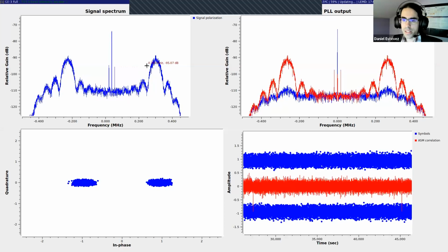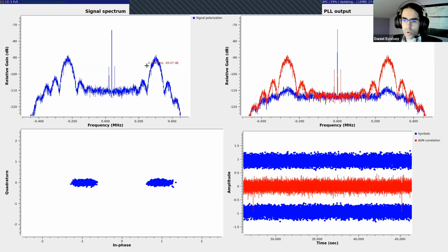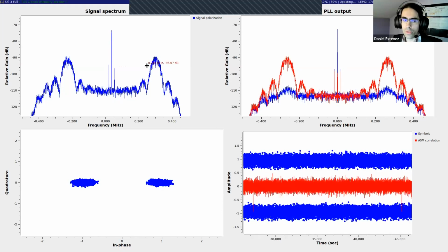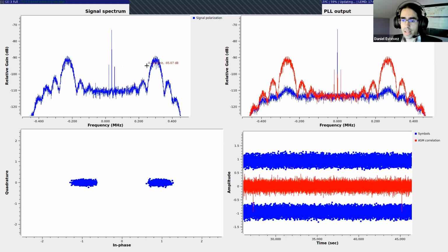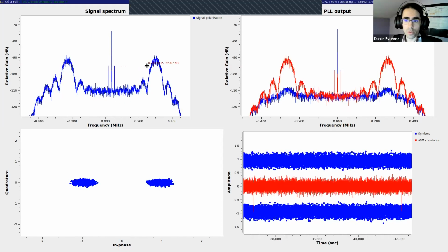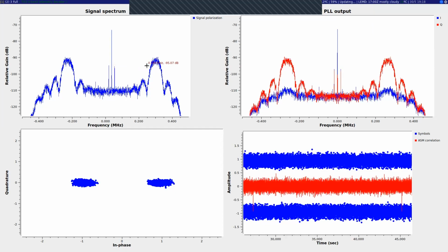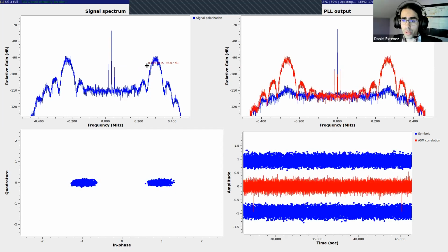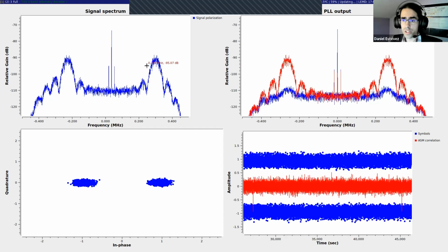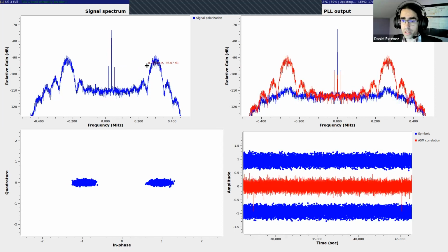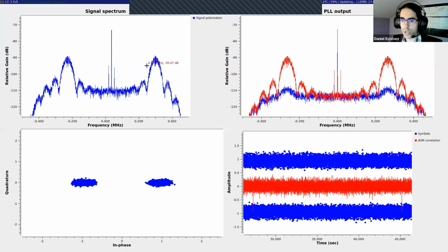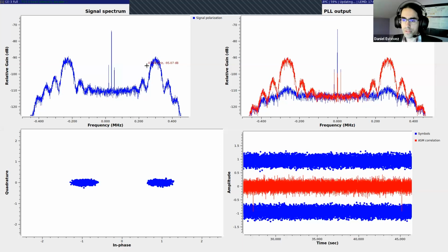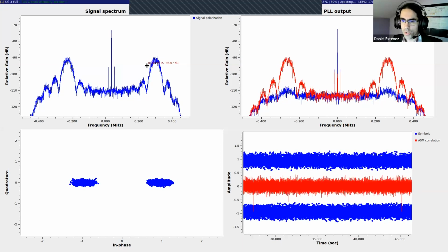the X band is very crowded. It's only 50 megahertz. All the deep space spacecraft share it. And there are a bunch of spacecraft on Mars, up to the point that radio frequency interference between several spacecraft on Mars is starting to become a problem in some very specific situations. So spacecraft are limited in the bandwidth they can use.